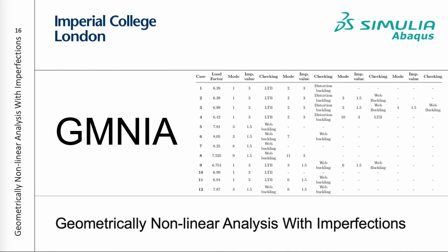By testing different scenarios with a bias involving the modes with the lowest eigenvalues, the most critical combination can be determined. As higher buckling modes have little chance of occurring, tests conducted mainly contain the most critical LBA mode number 1.